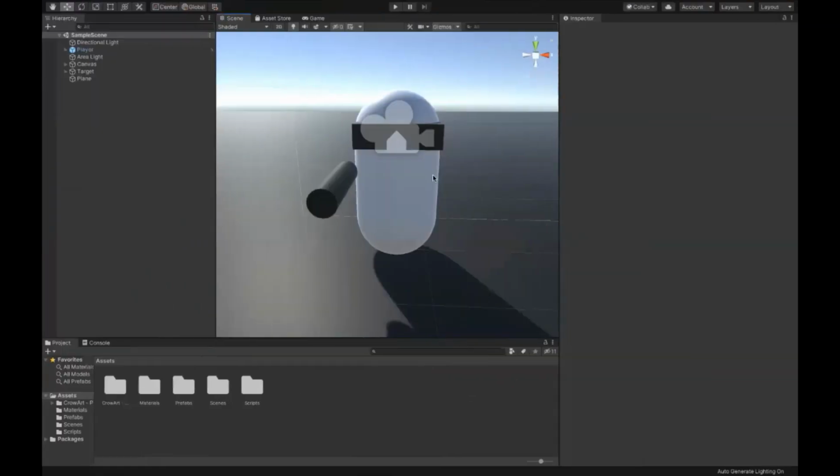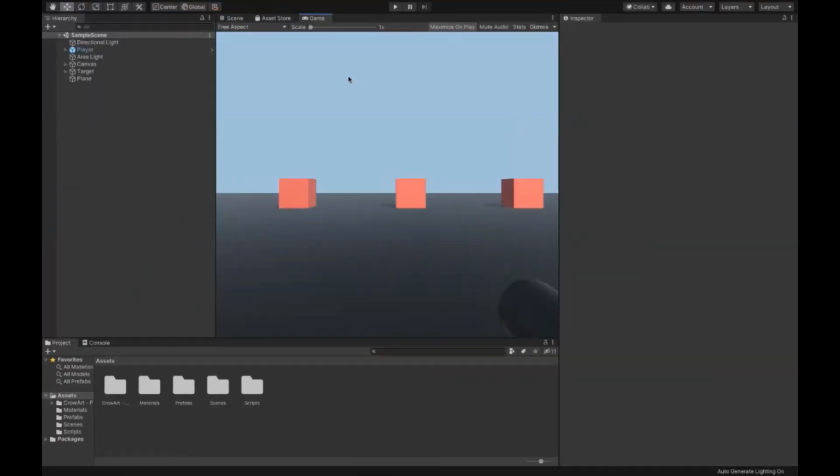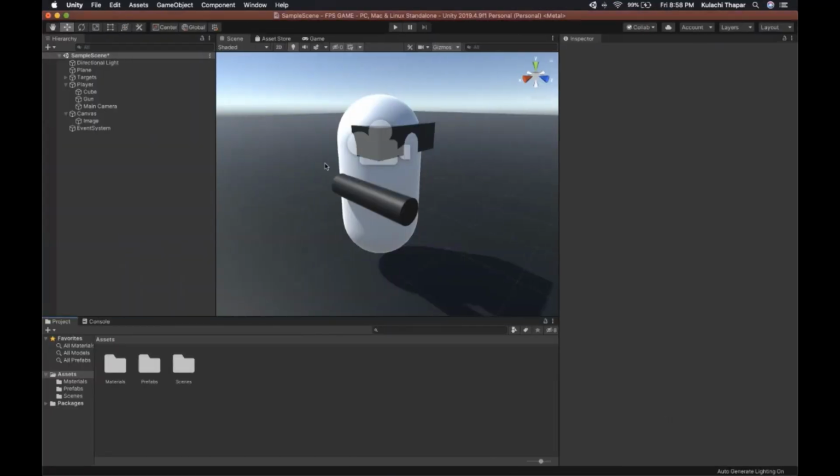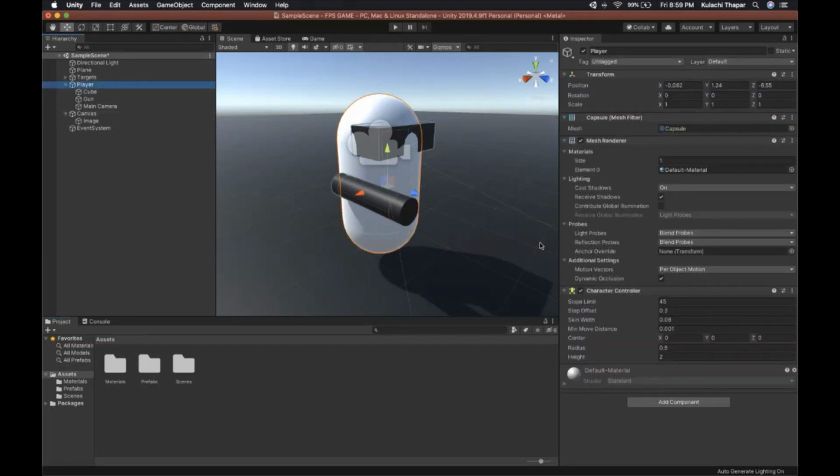As you can see, when you're moving, your whole body or the whole player is moving front and back. So that is a property of your entire player. What you can do is go to your player, click on add component like we did before, and there's an option called new script. So we click on new script, and let's say we name this player movement.